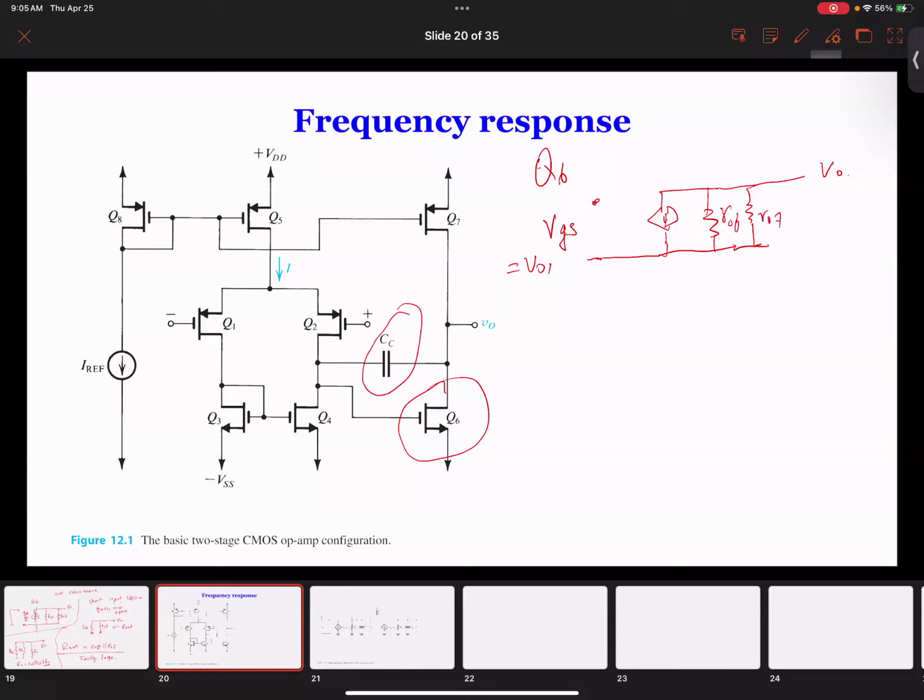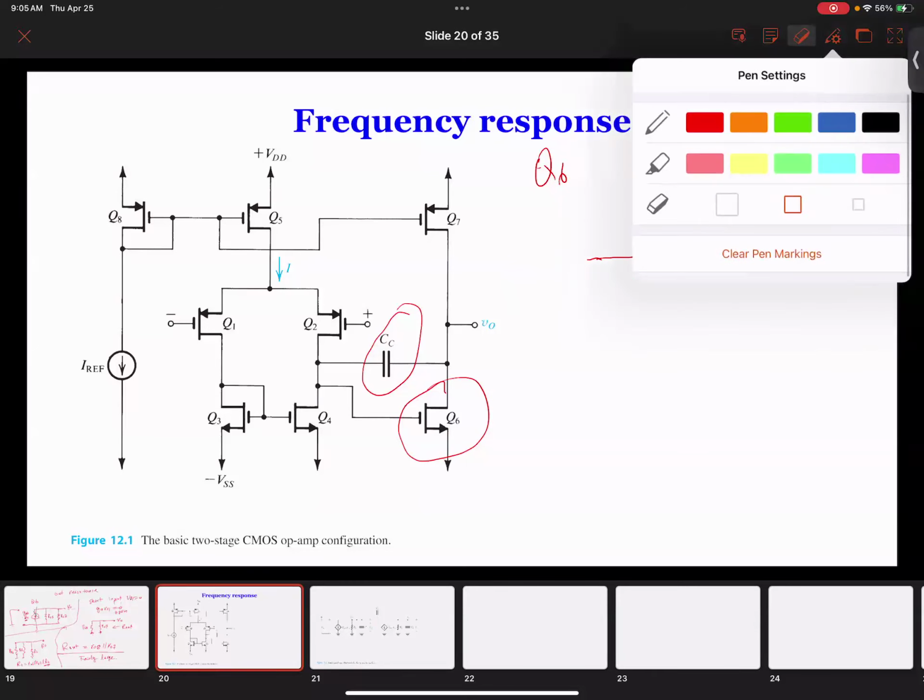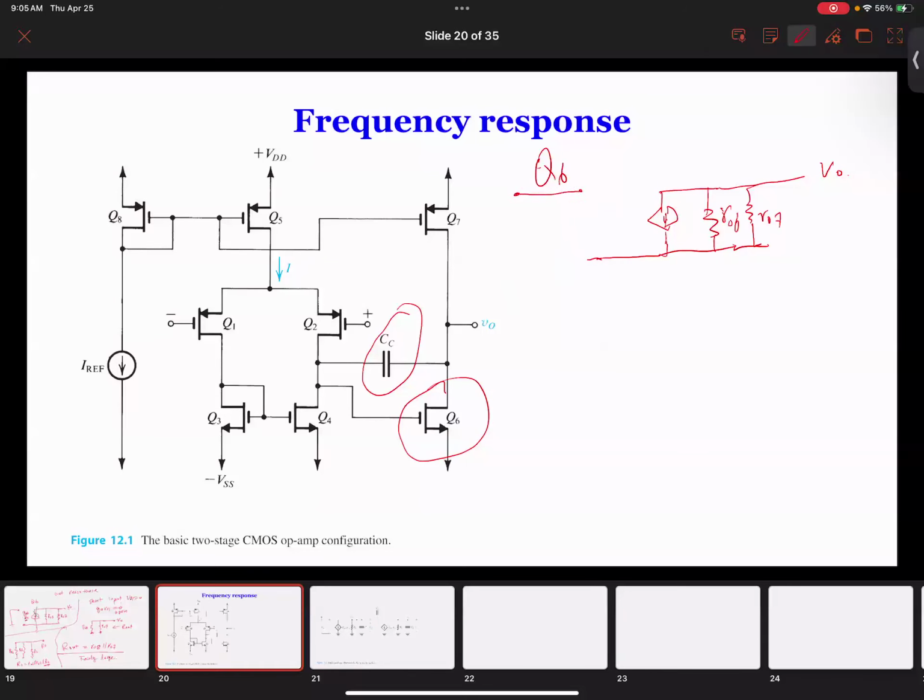When we want to do the frequency response for the high frequency range, this circuit does not impact the really low frequency, so we are basically skipping that part, but we can certainly do the low frequency response. When you have a low frequency response, usually there are capacitors put in the circuit. But in this case, we don't have any capacitors at the input for DC biasing, things like that. So we're not really worried about low frequency response. We're mostly focused on the high frequency response.